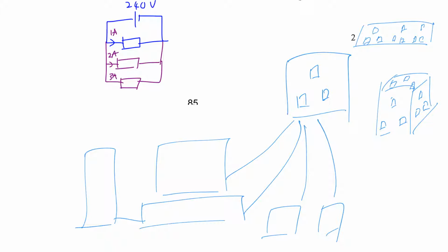Do you understand? So this wire here from the power company to your house, and then from your house to that socket that you have here. Which means to say it is the wire behind the wall, behind the socket. So if this was in the wall, there will definitely be 3 wires running back to your circuit box. You understand? So the earth has no function except during leakage, but the live and neutral wires will carry the current. So when they carry the current, the more appliances you connect, the bigger the current in these 2 wires behind your wall.